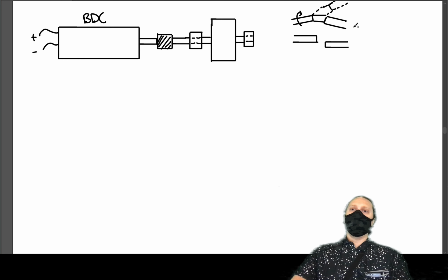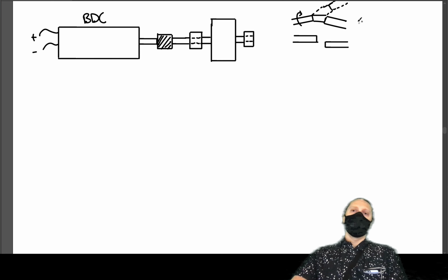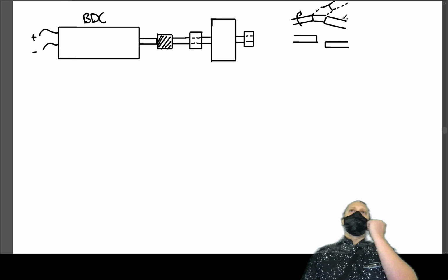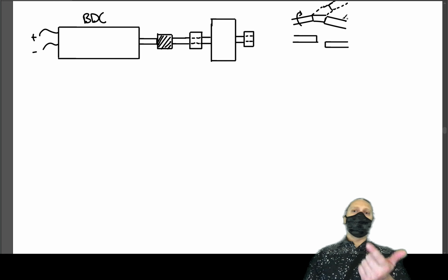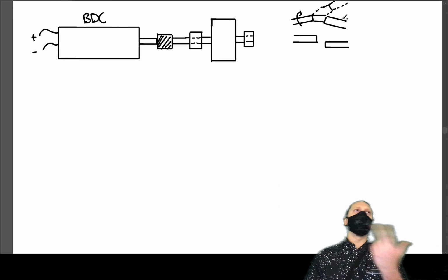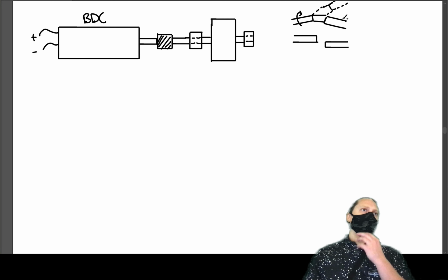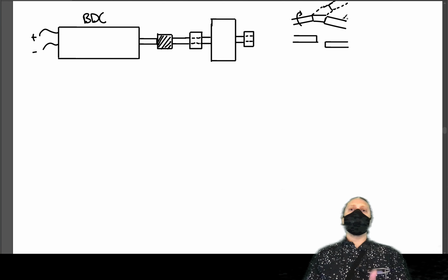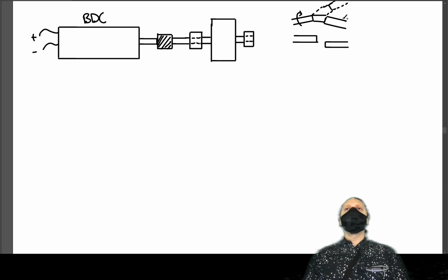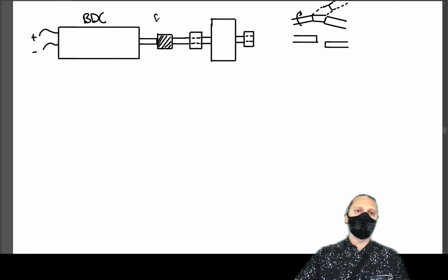Well, it's supported by bearings over here. That shaft doesn't want to move way over there, so it's going to resist that. It could bind. It could totally break the coupler. It could break the bearing. It could crack the bearings. It could wear the bearings down quickly if it's just a little bit misaligned and still rotates. It's bad news. You can't rigidly connect those two shafts together with a coupler. So what you do is you put on a shaft coupler that's flexible. So this is a flexible